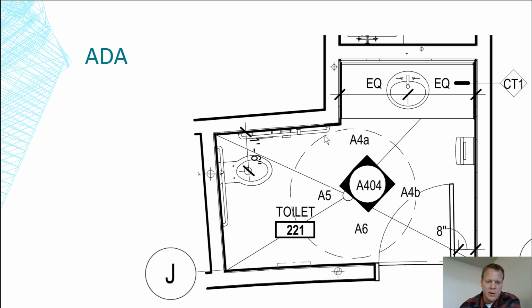And this grab bar right here. It doesn't necessarily say that the toilet room is ADA compliant, but one dead giveaway of where the ADA compliance is: see this circle right here? When you see these dashed circles or squares that don't make any sense, those are the spaces that the designers put in there to ensure that the ADA compliance is there.